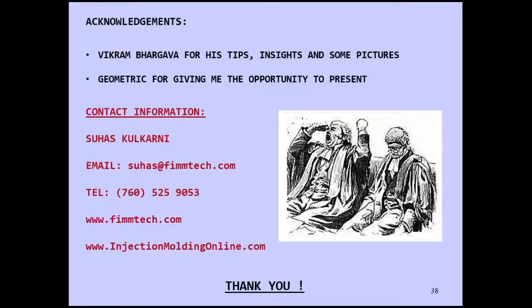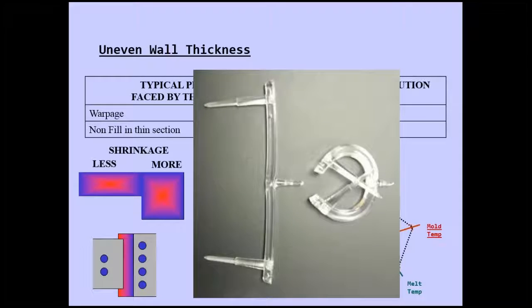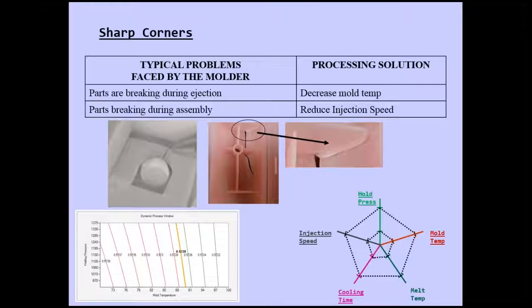Yeah. So basically, one of the main things that you have issues with is what you just said, when you try to take care of the sink on the parts. That is one big thing. Second thing is sharp corners, which I think is the biggest thing I always see that have issues as far as part designs. Then thin walls. I don't believe I brought thin walls in here. I should have also included thin walls. Thin walls is another huge thing, because when you have thin walls and you try to fill it out, at the end of fill, molders will try to pack that area out or increase the melt temperatures, and that causes quite a few problems.